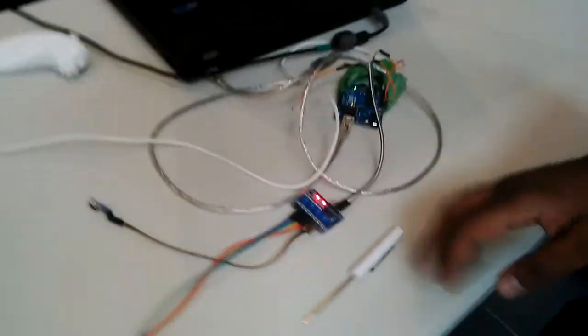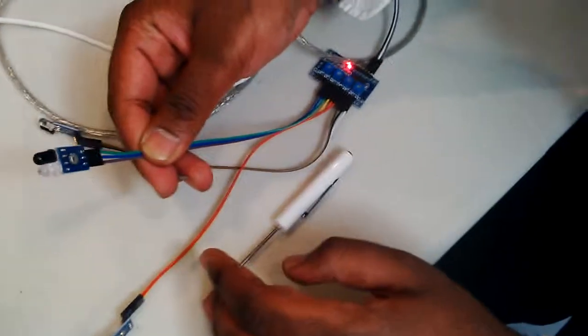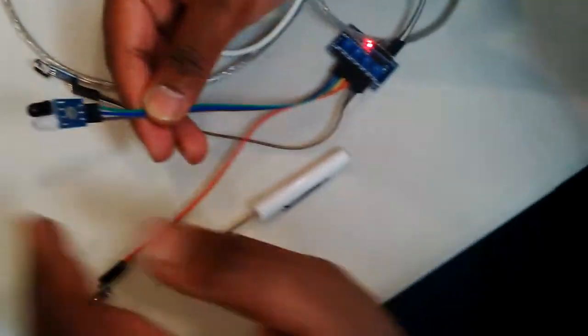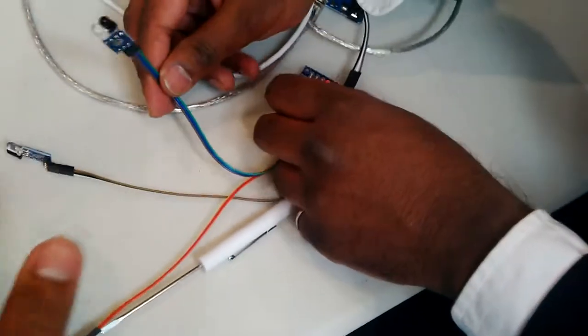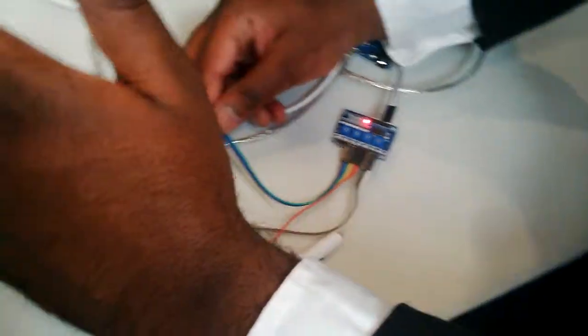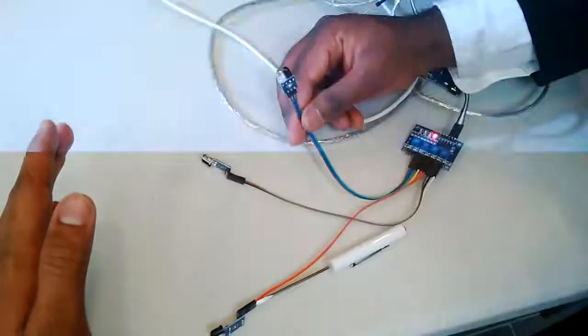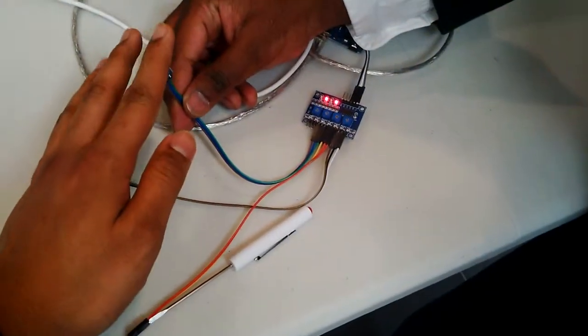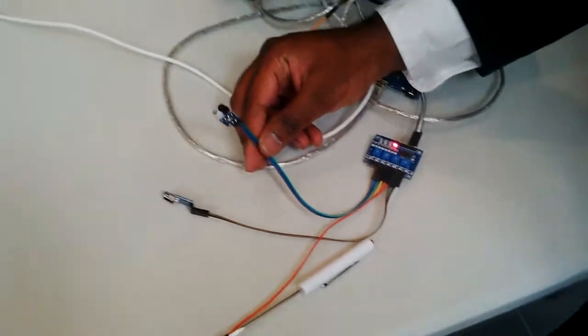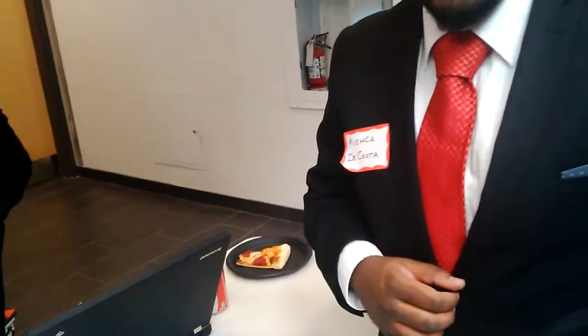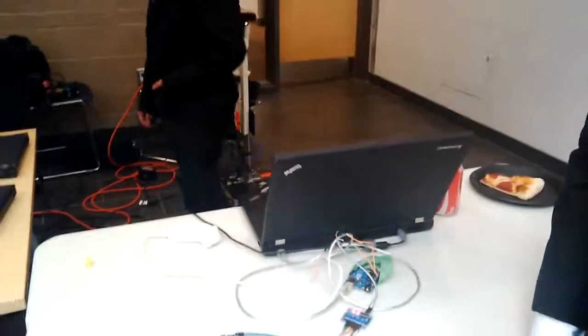The final thing I can show you here today is our emergency stop system. It's basically an infrared transmitter and receiver. When you bring your hand close to the transmitter, you can see over here that the LED comes on. So as I bring my hand close to the sensor, the LED comes on. This is basically the emergency avoidance system. The path planner should technically keep the robot away from colliding into any obstacles, but just in case the path planner fails, this thing will ensure that our product remains safe.